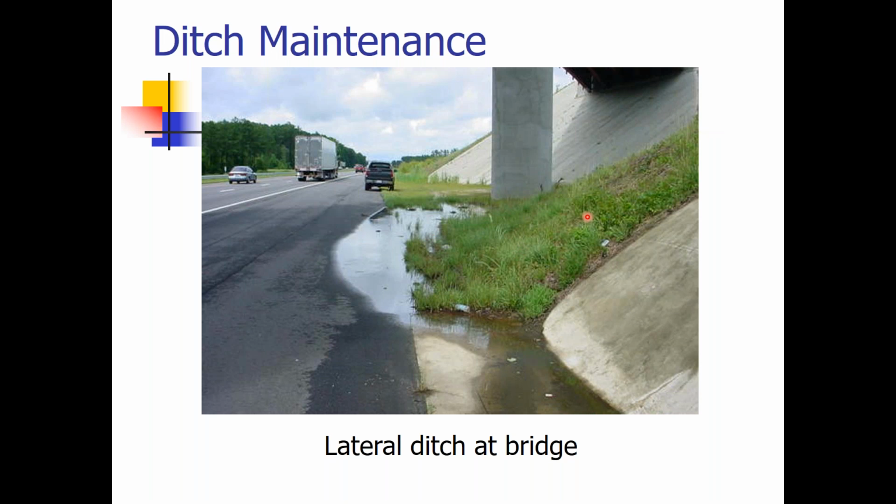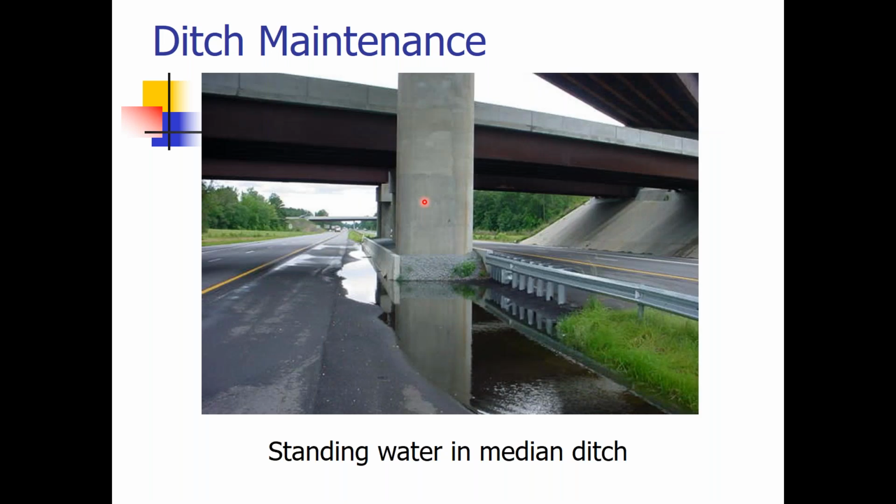Okay. And each of those things, Victoria, that you're bringing forward are all correct. Again, we have to maintain this. We have to cut it back. Otherwise, we're allowing water to infiltrate the roadway. And over time, you're going to start having cracking take place. It's very clear. But the problem is we're working with less people and less resources, but it is important to save us more money in the future. We have to make sure that our maintenance program is keeping this stuff cut back. But let me show you something else.